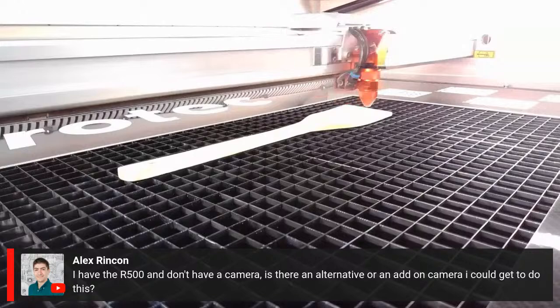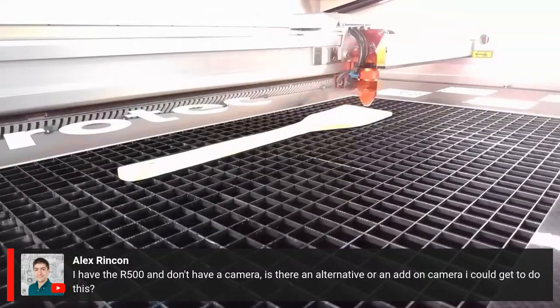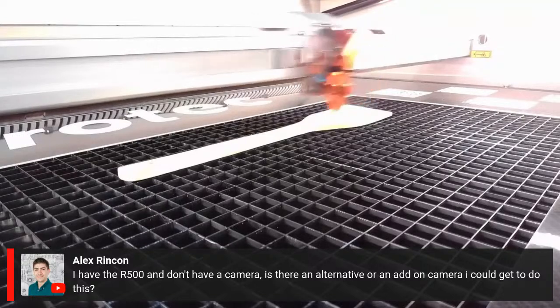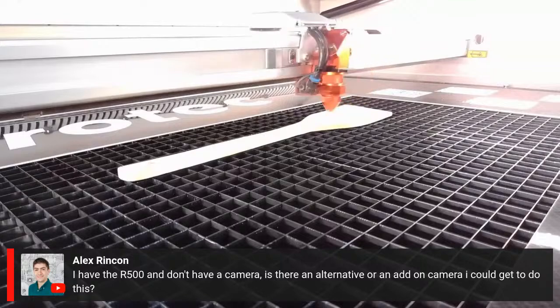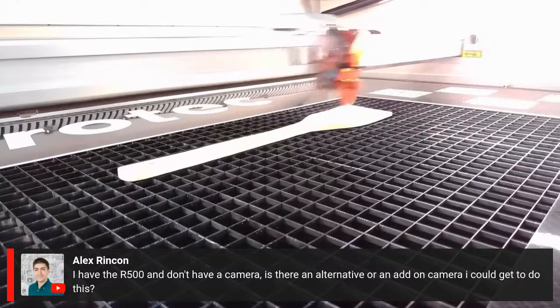So for you, the best method is going to be to use more of the traditional way of just jigging the parts. So having a base material, cutting out the profile. You'll quite often find though with something like this wooden part, the size and shape will actually vary just due to the tolerances of manufacturing. So sometimes you will have to have a bit of extra space on that jig itself just to make sure that you can consistently fit the part into there. But yeah, for that particular model, it's only on the Speedy 400 and the Speedy 360 where we have the lid camera options.